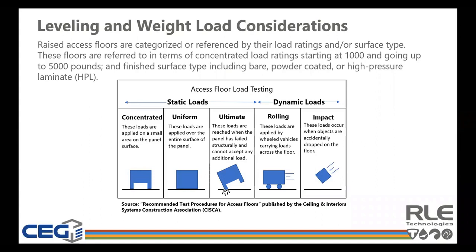It's also important to note the rolling load ratings of the panels in your data center, because that's typically how things are moved in and out of the data center. And keep in mind that rolling load ratings are typically less than concentrated load ratings for the same panel. I've worked with several customers in the last couple of years to replace floor panels that have been damaged and deformed from loads that have exceeded the manufacturer's weight rating specifications. And we had one customer last year who actually had 2 racks fall through their raised floor.